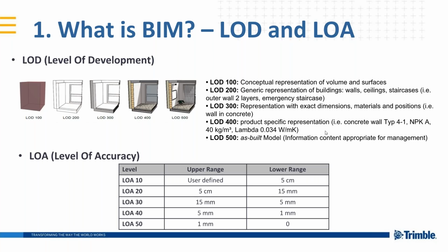So in each project specification, you will see the level of accuracy. You see here the levels that we can find. Also, probably depending on the country, you could also see slightly different levels. But you will see, for example, for the topographical survey outside, the LOA is 25 millimeters. So you can decide, okay, I can measure outside with my GNSS receiver because I'm achieving better accuracy than 25 millimeters. And then for inside, you will get 1 centimeter, 2 centimeters, whatever.